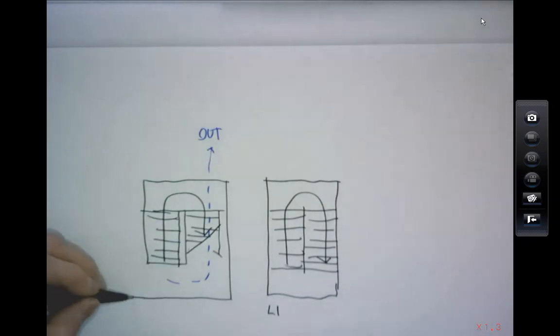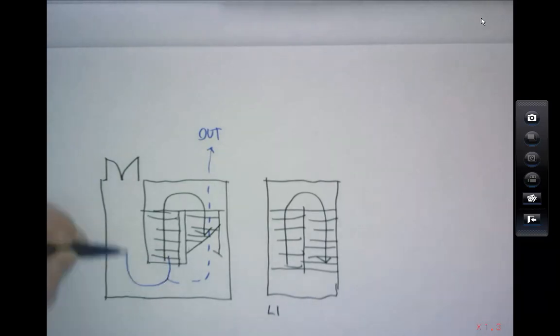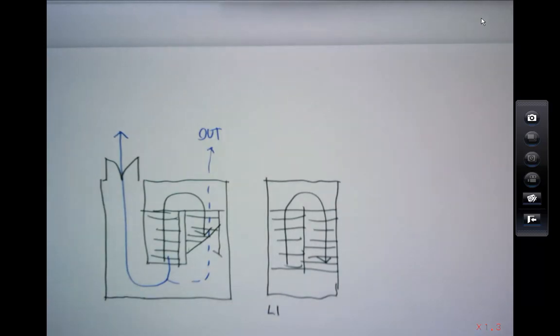So what you often have to consider at ground floor is a bypass. So you'd get to the bottom of that stair, and you'd go out like that. All right. Now we'll look at that when we look at the stair dimensions next week. We'll look at some options about how you could potentially get that stair high enough to get underneath it. But what it does mean is, with this bypass, subject to the numbers of people escaping, you could potentially expect people from the ground floor to escape through this zone, as long as the doors aren't blocking escape.